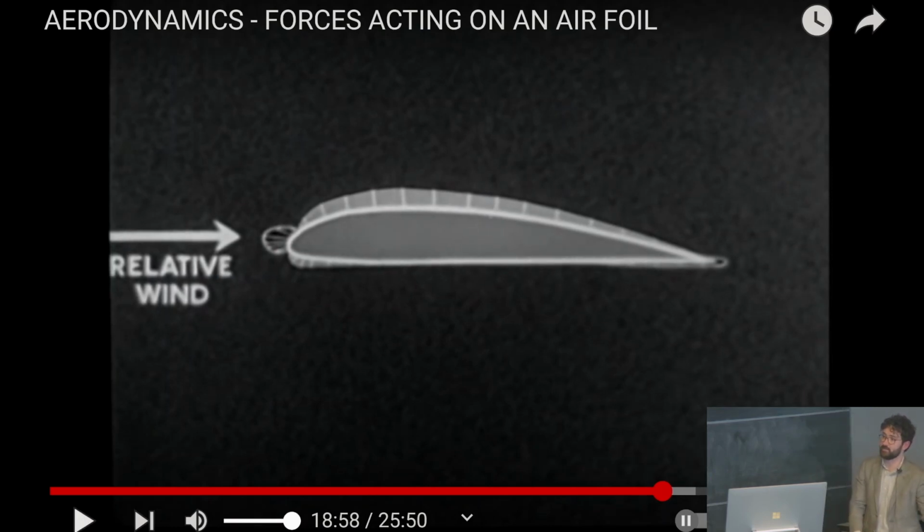I think sometimes when you need really highly accurate measurements, you can do that. And like I mentioned about the time response, the flow is usually steady for flow over an airfoil, so you're not worried about that time response issue with the manometers. If you take an instantaneous photo, you can assume steady flow in that case. So are there any questions about this?